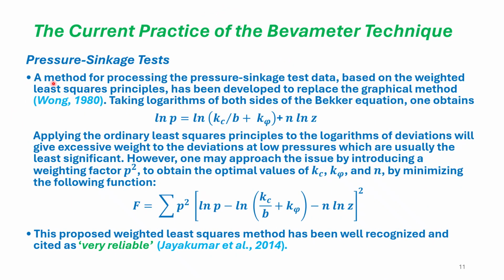A method for processing the pressure sinkage test data based on the weighted least squares principles has been developed to replace the graphical method mentioned earlier.